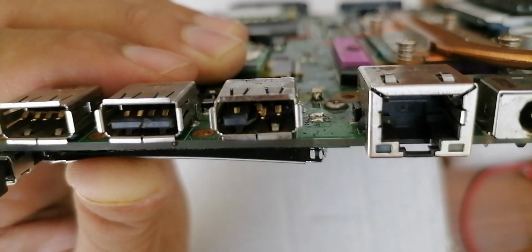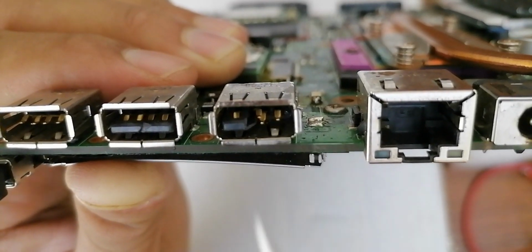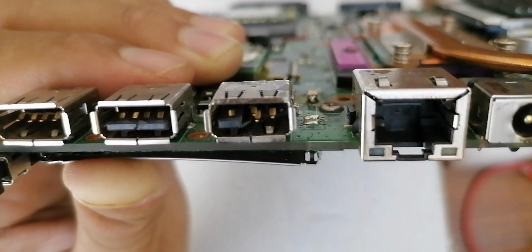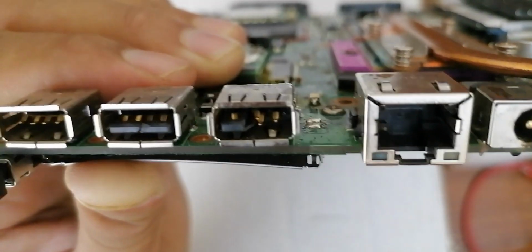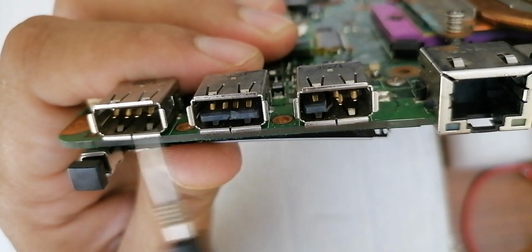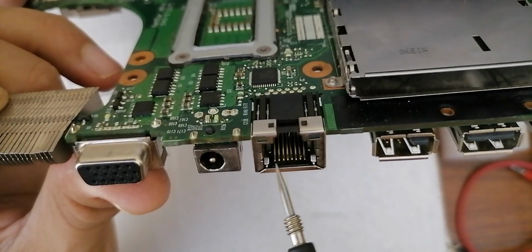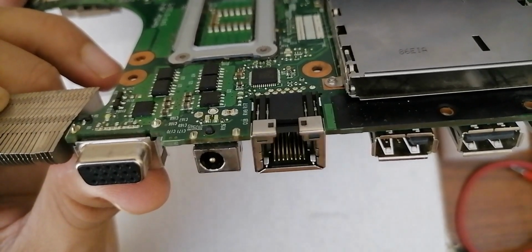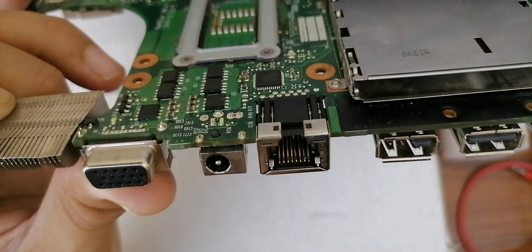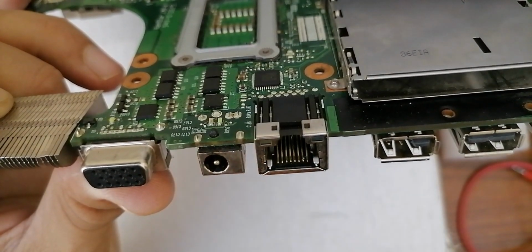So the first thing is doing visual inspection. The second thing is checking connectors, because also about 25 until 30% of failed motherboards are due to shorted connectors. Of course, all connectors, not just USB connectors, but all connectors, including, for example, the RJ45 connector. So as you can see, an RJ45 connector could also be a shorted connector. So please don't forget this step. So the first step, visual inspection. The second step, connectors. Okay.